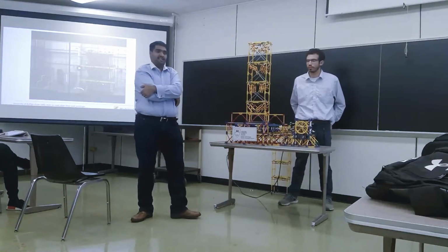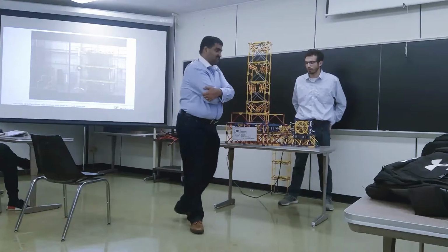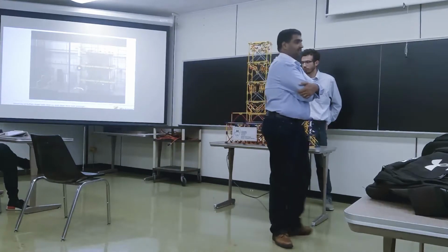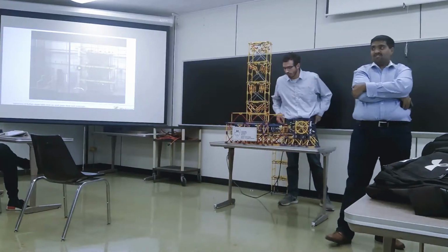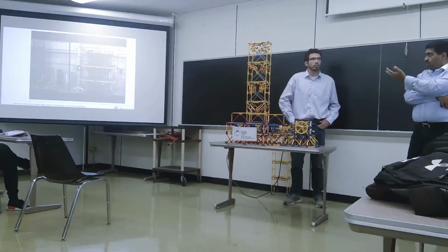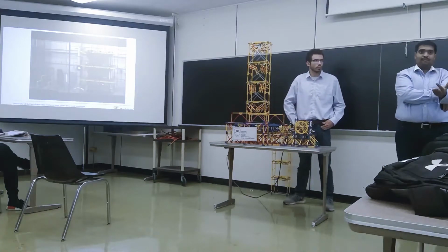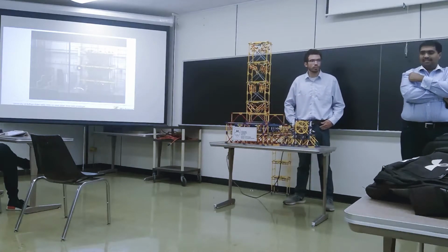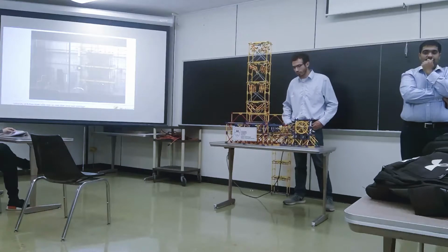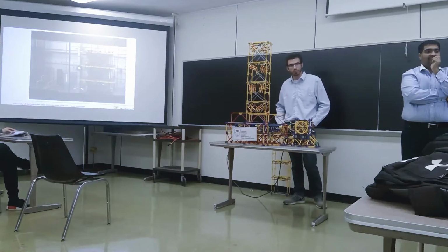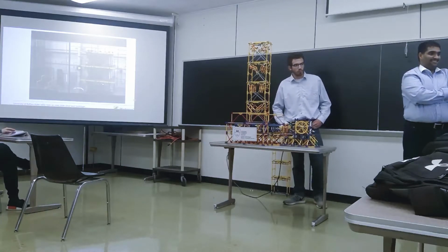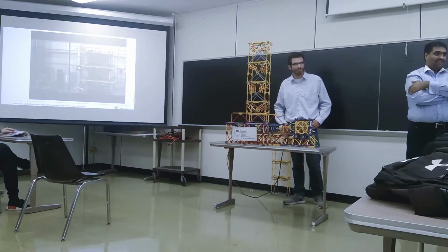Decrease. They decrease, right? So in structural health monitoring, one of the main things is we try to find the natural frequencies of the system and mode shapes of the system and track them over time. So there's actually a paper in IMAC, the IMAC conference, and this researcher has been studying a building for like 20 years. Same building.